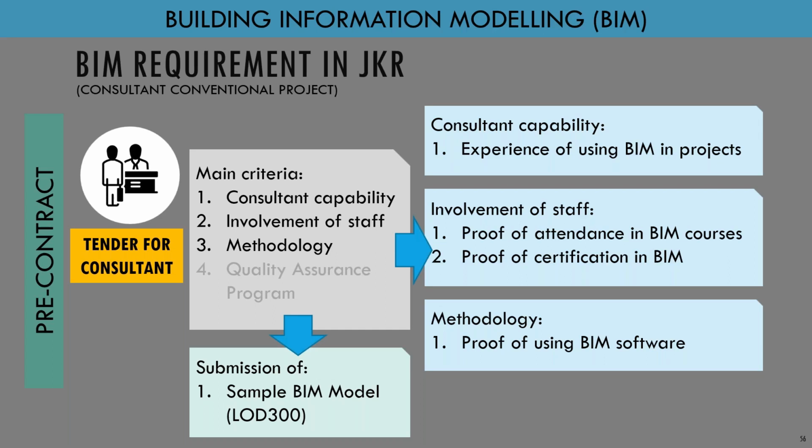Some consultants don't give a building model, but give a sample of a column only. It can't be like that, we want the whole structure. Don't do that, you need to submit the sample of the BIM model up to LOD 300. Okay.